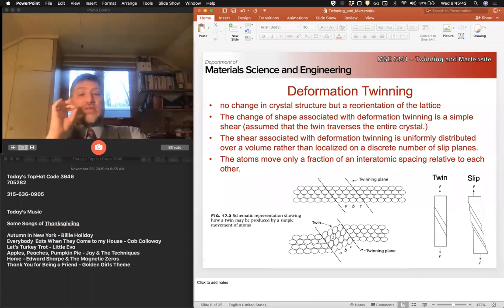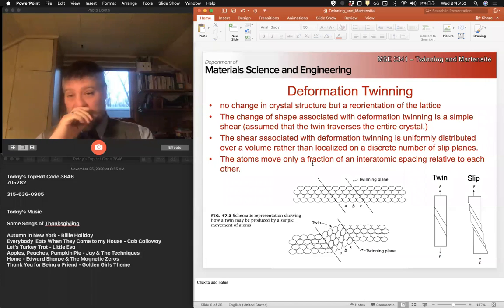Okay, so let's talk about twinning really fast, right? We're not talking about annealing twins here, okay? Annealing twins in metals happen because of growth accidents. The structure is the same, right? We still have the same type of mirror plane and stacking sequence faults that we'll talk about later, right?